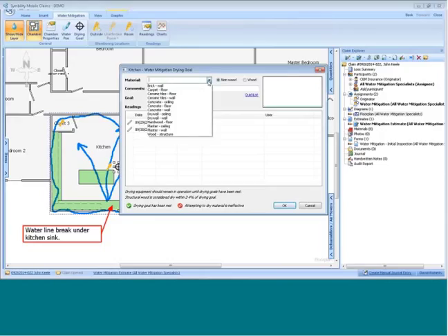We have all the most common types of materials that you would work with, of course, and let's say we're going to start with a wood structure. We're going to pretend this wood had some subflooring right in front of where that kitchen sink was. So I choose wood structure. It automatically indicates wood. And then I can put comments in here. And I can say wood subfloor in front of the kitchen sink. And I can set my goal at whatever I want. I'll just say 12% for this.